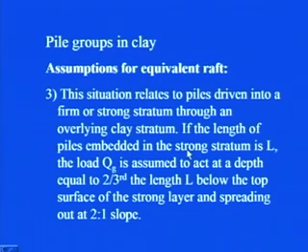So you simply take 2/3 of the length and from the top of the strong stratum you measure 2/3 of L, then you place the raft, and below that, in exactly the similar manner, you assume the load spread in 2:1 manner.